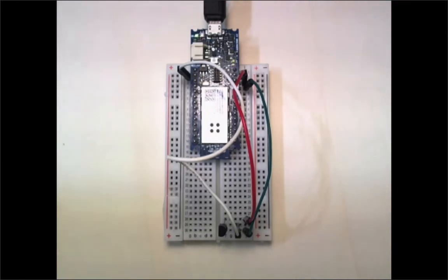The thing I wanted to show you is that instead of just having a simple logic that pulls data out of the sensor and sends it to the cloud, you can also put a little bit of logic in the device if you want. So this was just a simple example. In a real scenario, we wouldn't be using just the temperature sensor. We would be using a specific sensor that detects fire, and we would send that information. But yeah, putting the rule in the ARTIK Cloud is absolutely equivalent. And actually, in certain situations, it may be even better because you can change that logic in the cloud without having to update the code on your device.